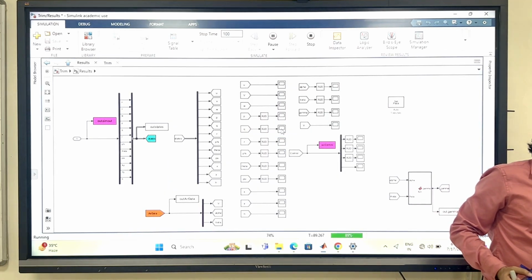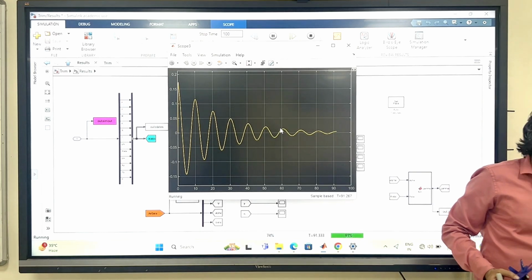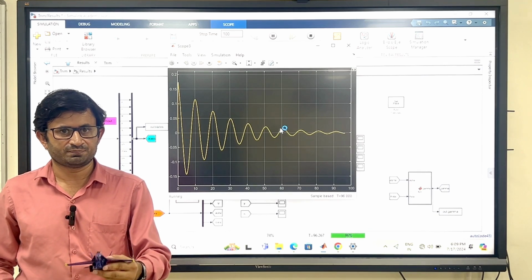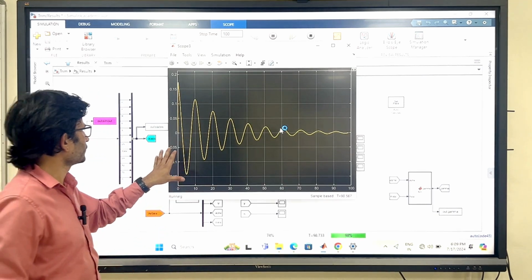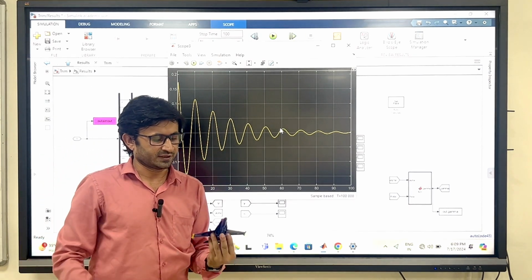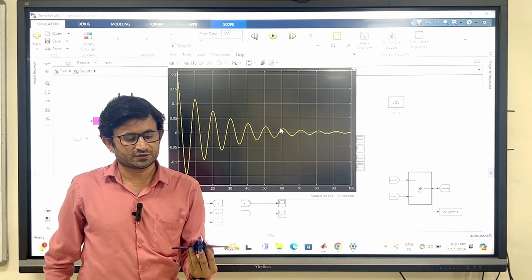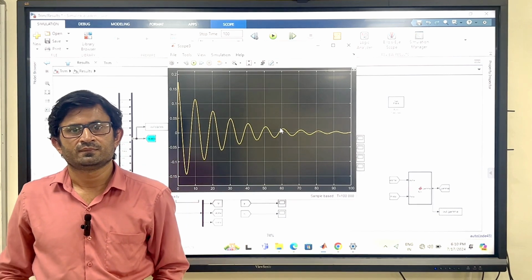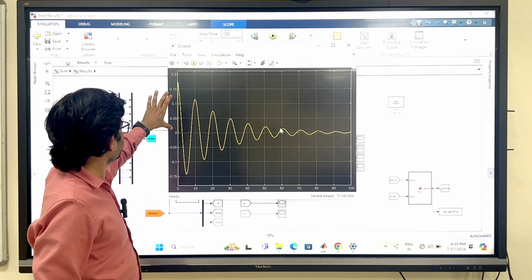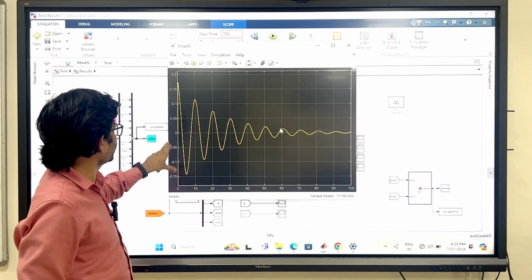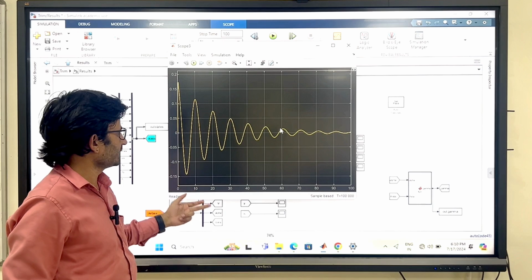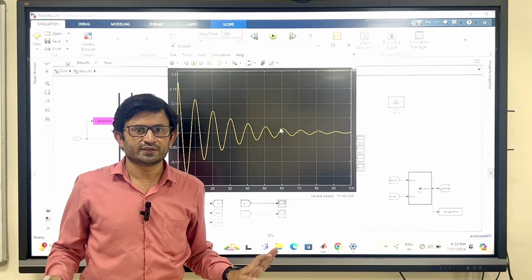Okay. Now you can see the pitch rate also. Initially, when you disturb, the aircraft has some pitch rate, and ultimately it will go to 0, right? When you give the trim condition, the aircraft takes some time. What I said in dynamic stability, it will take time to damp out. Similarly, it is happening here. And see, the y-axis amplitude is very less. This is degree per second. 0.05 degree, 0.1 degree, minus 0.1 degree is almost 0 only, right?